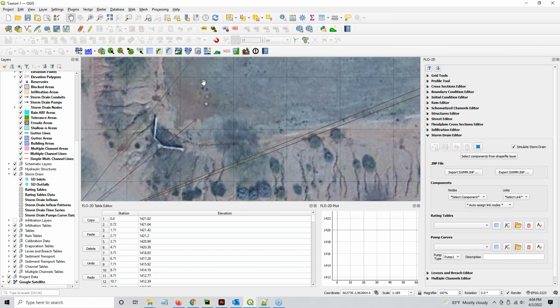Now, I set the node up here because the elevation of this grid element is high, since most of the elevation is coming from up on top of the head wall, not down on the bottom of that head wall. So I can put this feature right here, and then the invert elevation of this node would reset the grid element elevation of this cell. That's okay, we'll do that automatically. Or I just put it out here where it's a little bit closer, and then I don't have this chunk of low elevation right here. So either way you want to do that is probably okay.